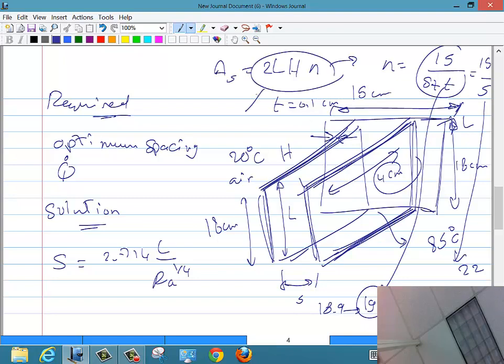But also note that in that solution, and I think that's the solution we used in the example also, he's neglecting the base area, right? But in real life, the base is also convecting. The air is sitting there and is convecting from everywhere, not just the base. So that's another approximation. Did anyone take the base into account? No one? All right.